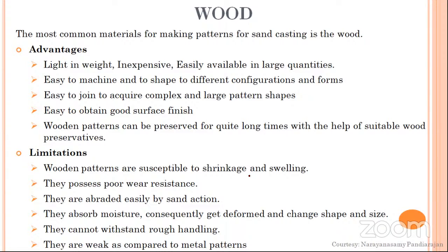The reason is, when you use wood for preparing a mold cavity, the mold is composed of sand, clay, and moisture or water content. Once you place a wood pattern and pour the sand and then ram the sand to get a mold, the moisture content present in the mold is absorbed by the wood pattern material.